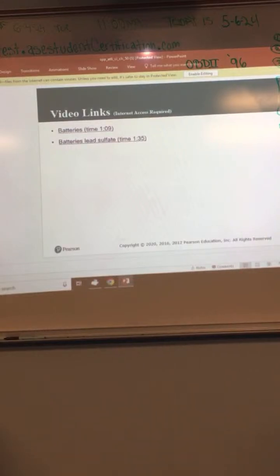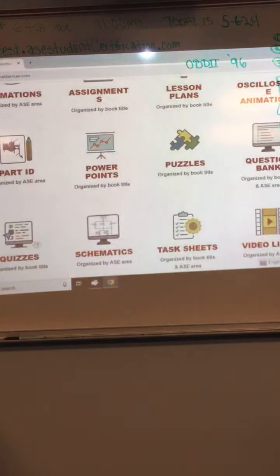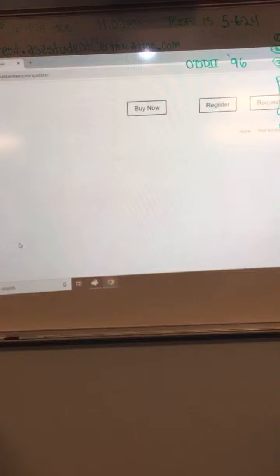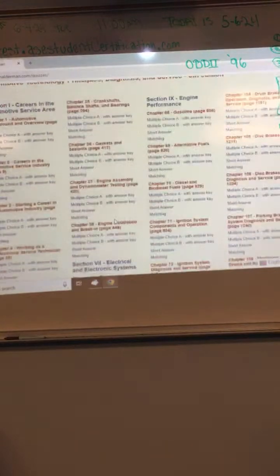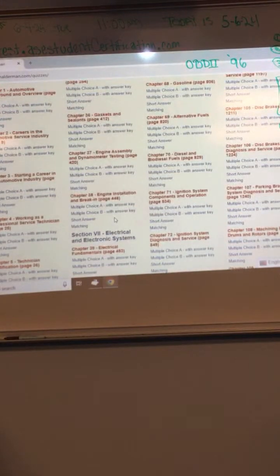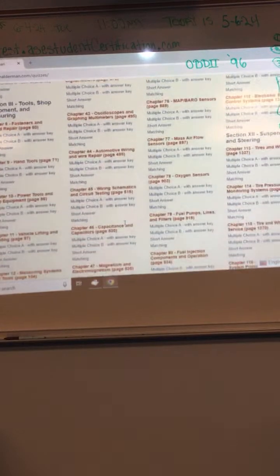So you know the rules, like don't tilt the battery, what was it, like 45 degrees? What happens if it lays flat on its side? Well, it'll end up leaking after a period of time. If you get a battery that's hot or smells like rotten egg, the battery's probably bad.